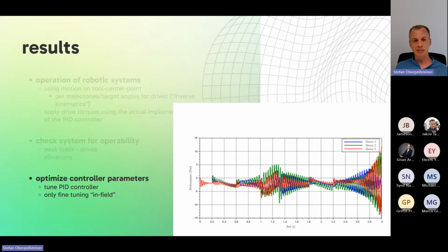That was the initial setup, how such a robot was shipped to the site. And as you see, this signal shows the torque in Newton meters for one picking operation from the simulation. It's a simulation result, and you see that there are high peaks and a lot of oscillation.